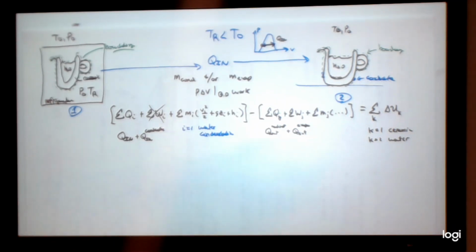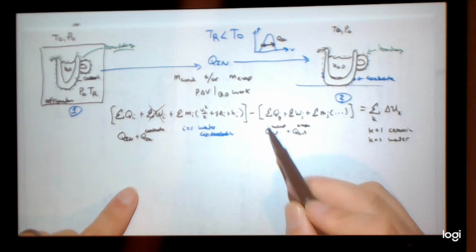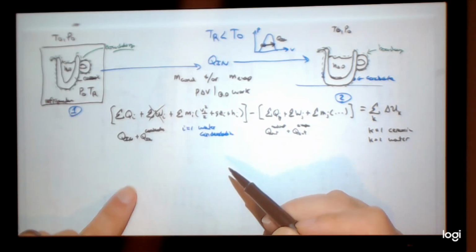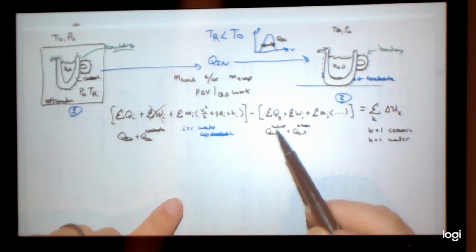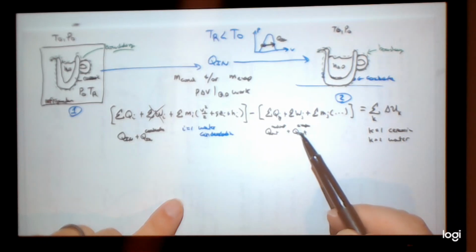Now, when I look at this, if I do the problem from taking it out, condensate's there, then later condensate's gone and water's evaporated, what had to happen? The same heat that went to condensation had to be that for evaporating the condensation. So these things will end up balancing out, the out and in. But if you were to say you just took it out and you got condensation there and then you stopped, then this wouldn't be here and you wouldn't have any evaporation.